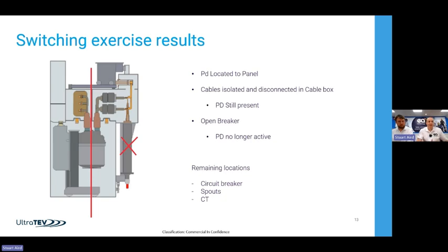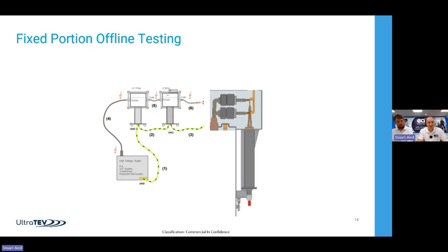After that point, you've got to where you can really get with non-intrusive, and the next step is to start doing an offline measurement, energizing each part of the switchgear individually, down to the component level, to determine which of the components may have partial discharge. The customer took a number of measurements and determined that they wanted to narrow this down much more. So we went to site with a 50 hertz full frequency power supply, a couple of coupling capacitors, and a smoothing capacitor, and then we can detect.